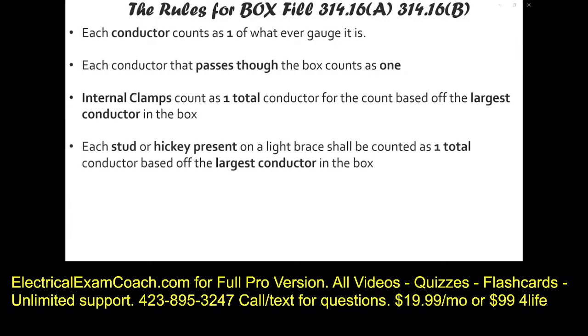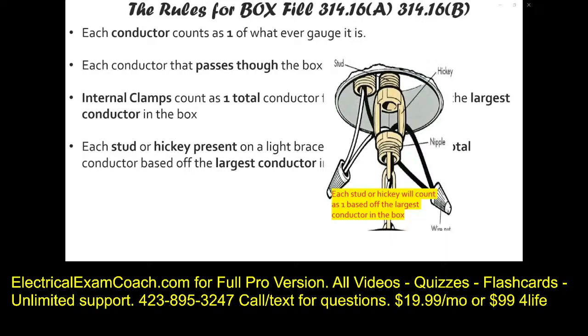Next, each stud or hickey that is present in the box shall count as 1 total based off the largest conductor that's in the box. Now, these are really old words, probably from the 30s if I had to imagine, but they still use them on examinations today. And this is what we're talking about. Imagine that we're hanging a chandelier. This we would call the stud or the nipple.